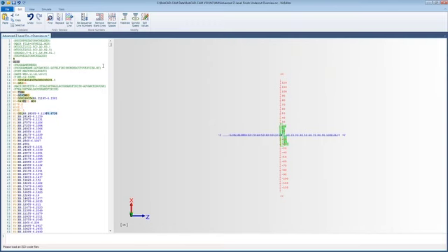But the remove blank lines and remove spaces are something you should never have to do in here, unless you're trying out a post for the first time, or unless you wrote that code by hand and you put spaces in it. But blank lines and spaces are things that we can handle inside the post processor. And if you don't want them, let us know and we can turn them off.